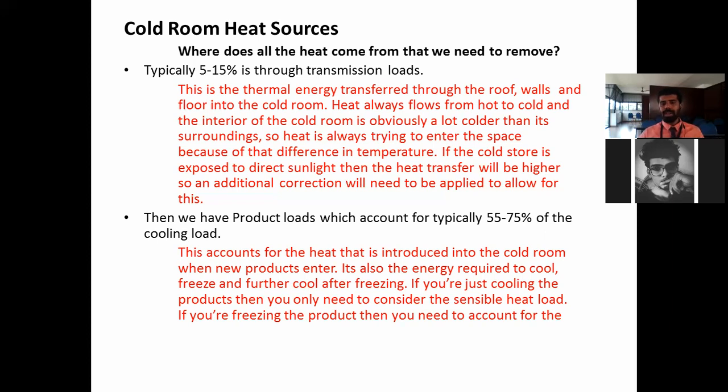If you are just cooling the product, then you only need to consider the sensible heat load. Sensible heat, you know that there is no phase change, right? There is no phase change, only sensible heat. So if you just need to cool, you need to consider only the sensible heat. You know what is sensible heat and what is latent heat. Sensible heat means you can sense it and there is no phase change. But in latent heat, there is a phase change. The water will be changed to ice, or ice will be changed to vapor.